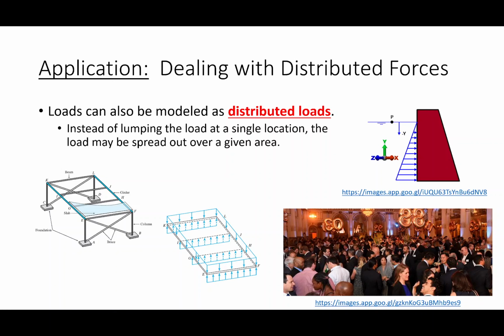Now how do we as analysts deal with loads that are not concentrated? Well, the way that we handle them is we sort of turn them into concentrated force effects. Now how would we, for example, turn this triangular load into a concentrated force? Well, what we would want to do is replace it with a single vector, okay? Now, what would the magnitude of that vector be? It'd be the area of the load.